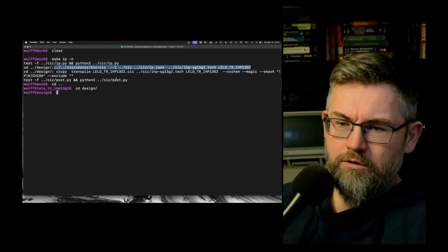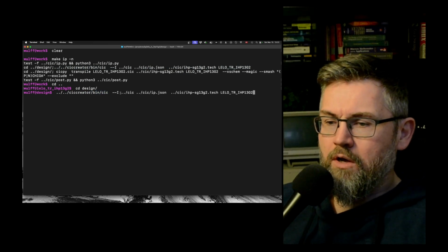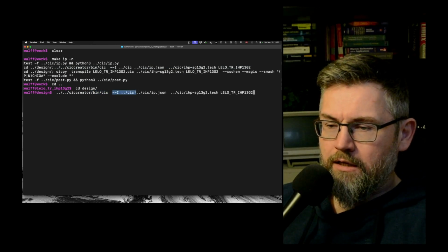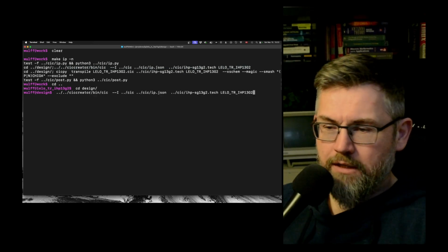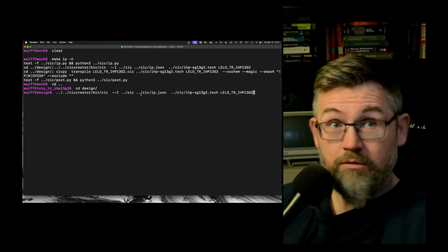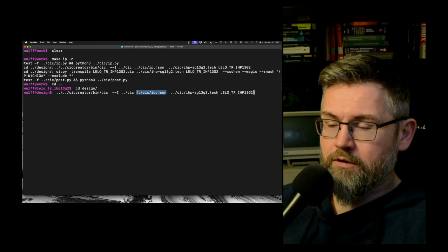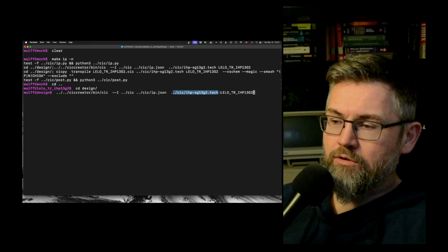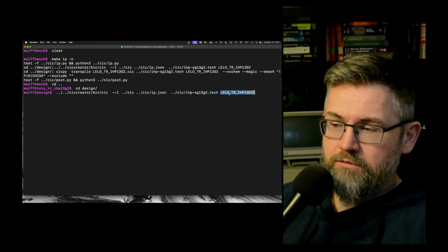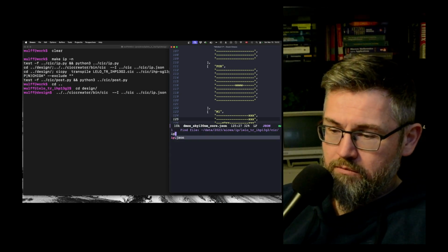So what it'll do, it'll run this CIC program, CIC creator, and it'll give it a library location, which is the folder I'm in. So that's the CIC folder I showed you earlier. That's where it's looking for JSON files. And it will give it the one JSON file, the IP JSON. And it gives it the technologies file, and it says, okay, generate the library, call this. And let's look at that IP file.